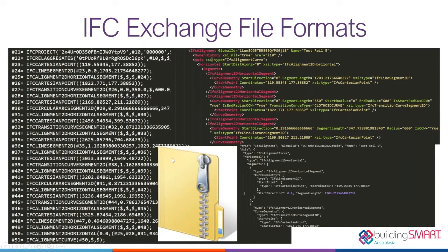There's also another agreed convention around sending or sharing an IFC file, and that's IFC zip. If your software doesn't support IFC zip, it's really just a zip file as if you'd encoded it in any other technique, including Windows File Explorer. You can change the file extension to .zip and extract the file, and you'll find inside it an IFC or an IFC XML file.